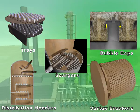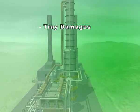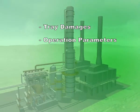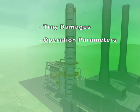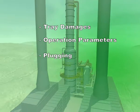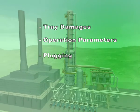Other subjects covered include causes of tray damages and the results thereof, the effect of changing the operation parameters like reboiler temperature and draw rate, causes of plugged trays and distribution headers and their symptoms.